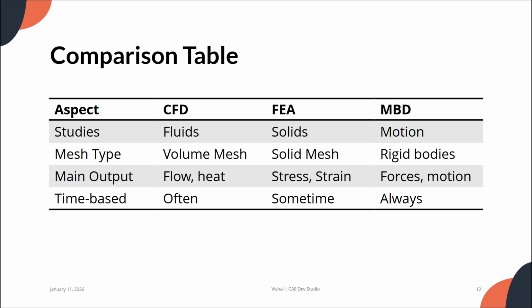How about the time base? In CFD, properties are often time based. In FEA it's sometimes time based. In MBD it is always time based. Based on time, how much the decay is going to be and how much the part is going to last, this is what the analysis provides.